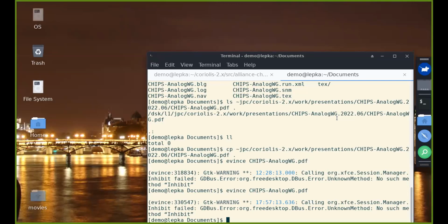I like your slicing floor planning stuff. Is there some way early at the placement stage to also get a wire length metric or something like that in order to determine whether you have a good placement without having to run the simulation itself? Just being compact doesn't necessarily mean that the wires are short.